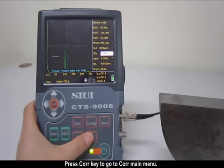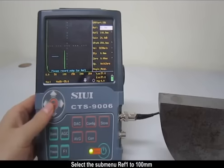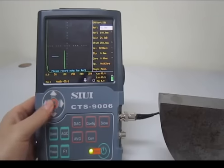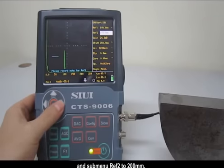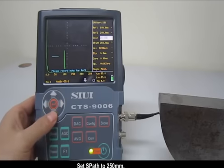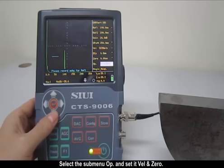Press Correction key to go to Correction main menu. Select the submenu reference 1 to 100 mm and submenu reference 2 to 200 mm. Set aspect to 250 mm. Select the submenu option and set it to velocity and 0.